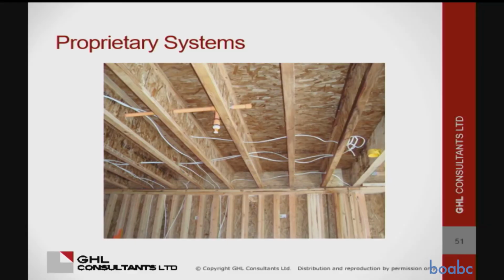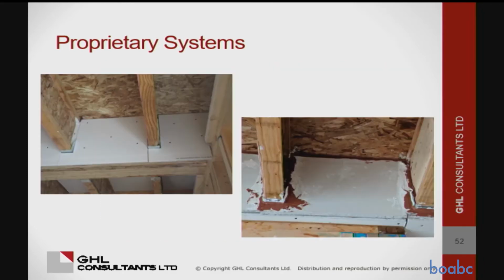So what you end up with, and that's just a picture of, obviously, the floor and the rim board, is this messy, hideous thing that somebody's doing during construction. And then because of the shape of the joist, you've got to cut all these little stupid pieces and put them in. And then it's like, do we have to mud and tape it? Maybe we should just blast it with FS1 and be sure. It's like, oh my God, what a mess. And it happens like every day.